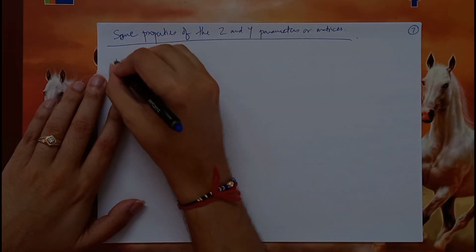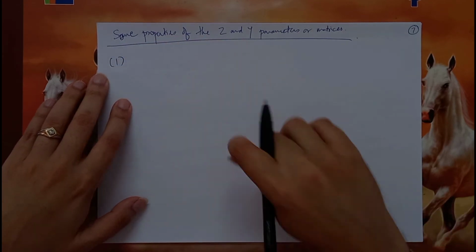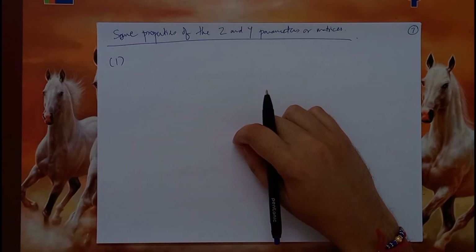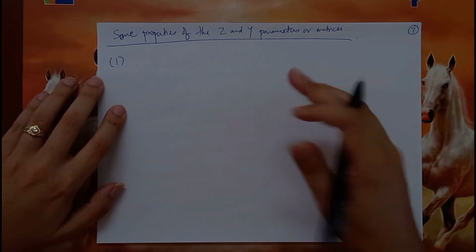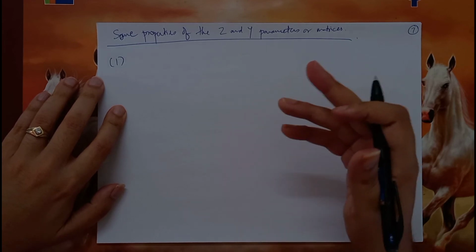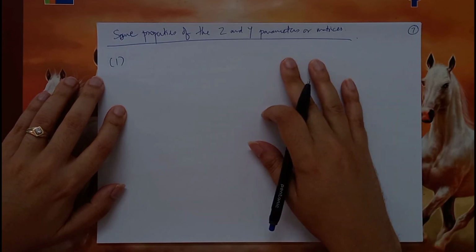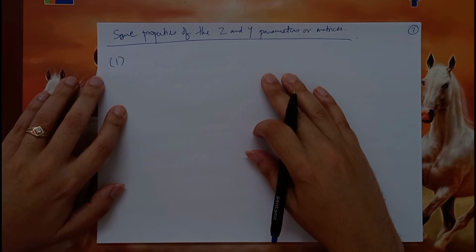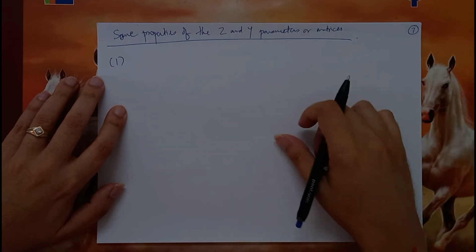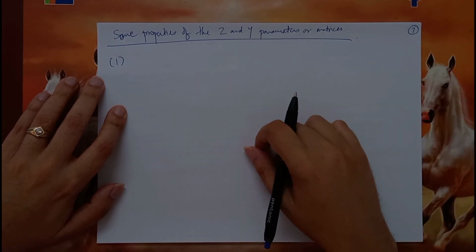So the first property is if any of the elements in the Z matrix or Y matrix is real, that means the network has resistive or conductive elements. So the moment you see that the network has a resistance element or a conductance element, it means those elements will dissipate power. Therefore the network is lossy.